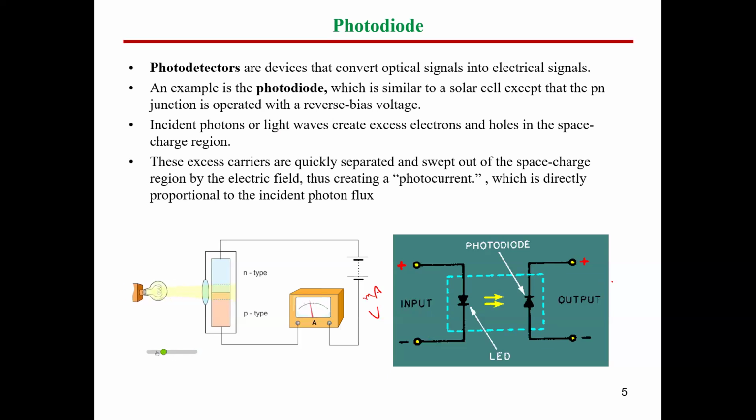And by the end, we'll have also a source, or the output here is going to be several milliamperes and voltages as well. What's the benefit of using this now, since the output signal and input signal can be compared together or very close in terms of values? So the benefit is to have isolation. Isolation means the negative here, this ground, let's say this is ground number 1, is different to that ground. This is ground number 2. So we achieved here the isolation.